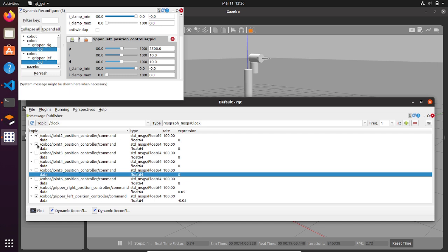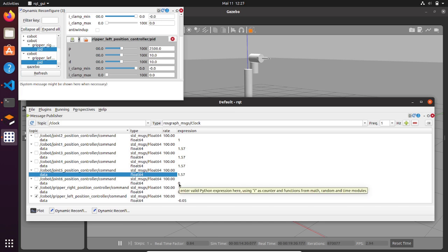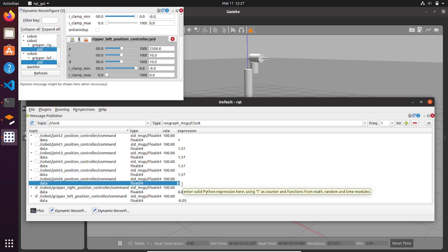So let's make another thing, and let's set for each joint 90 degrees of angle, and see at what position the TCP is going to go. So for example, we are going to set 90 degrees for joint 1, 1 radian for joint 2, 90 degrees for joint 3, joint 4, joint 5, and for joint 6 let's put a value of 2 in radians. Okay, so let's